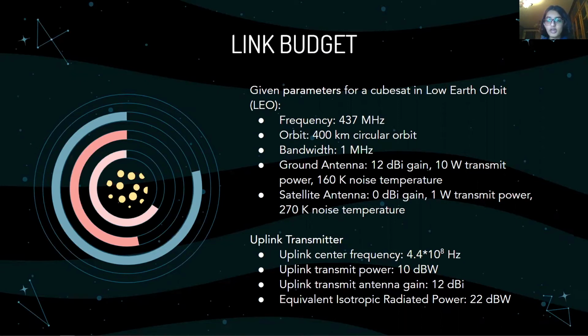That doesn't change. In a real-world scenario, this assumption would obviously not hold. Finding a more representative orbital height and analyzing its effect on the link budget are things that our group still needs to work on. However, using this given orbital height, we were able to calculate the shown values for the uplink center frequency, transmit power, antenna gain, and EIRP.